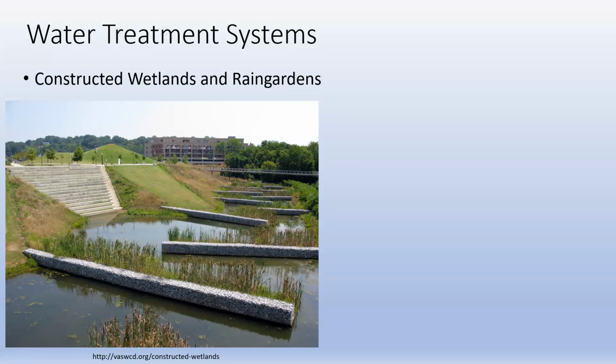That's completely by design. By slowing down the movement of water, that's going to allow some of those sediments to settle out. The water's not moving at that speed where it's going to transport very far. So that those solids settle out and that helps there. Plant material is great for it. Those plants are going to take up your fertilizers, right? They're plants, they love fertilizer. So you get some plants there that thrive in those aquatic situations and really rapidly take up N and P,